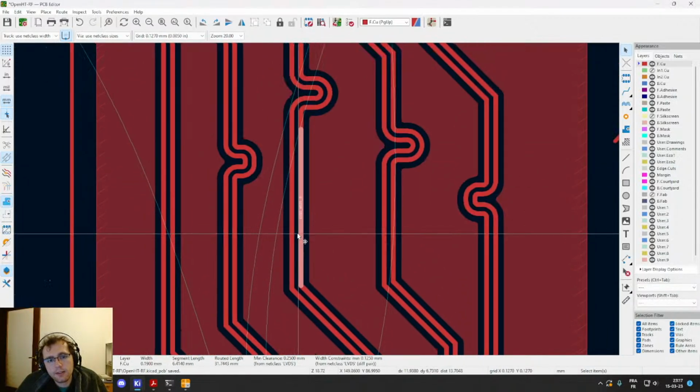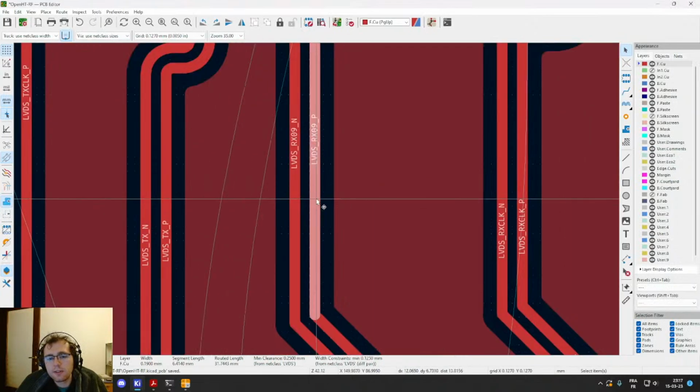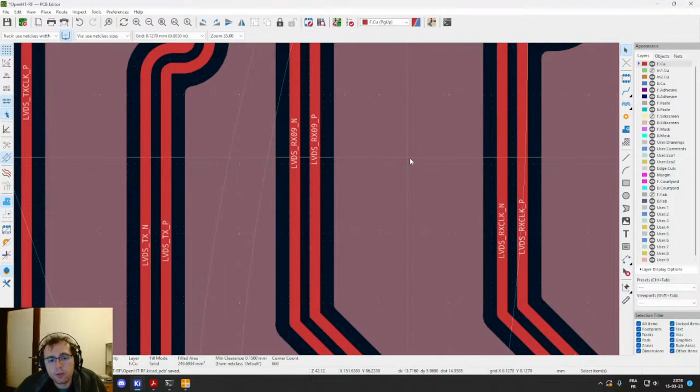So this is a track, an inductor if you want, which is gonna have high speed signals, so generate a magnetic field which is gonna vary at a few tens of megahertz, few hundred megahertz, 128 megahertz, I think. And so this is gonna generate a high frequency magnetic field, which is gonna generate eddy current, induced current in the ground plane around.